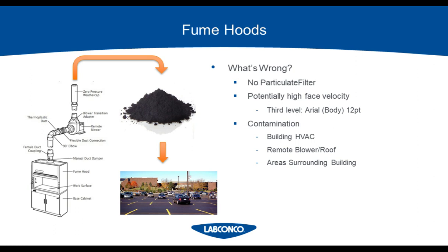Normally, with chemical fumes, chemical vapors, those items are ejected into the airstream and diluted very rapidly. They don't have a physical mass, they're just a chemical vapor that dissipates over time. But with nanomaterials or powders, those are physical items that don't have a way of being dispersed easily. So they end up in bad places. They end up in the ductwork, they end up in the parking lot, they end up in the blower and on the rooftop. All the areas where air passes out of the hood and eventually onto are places where there could be contamination. Well, that's not a great use for a fume hood because there's really no way to stop the nanomaterials at any point and contain them.